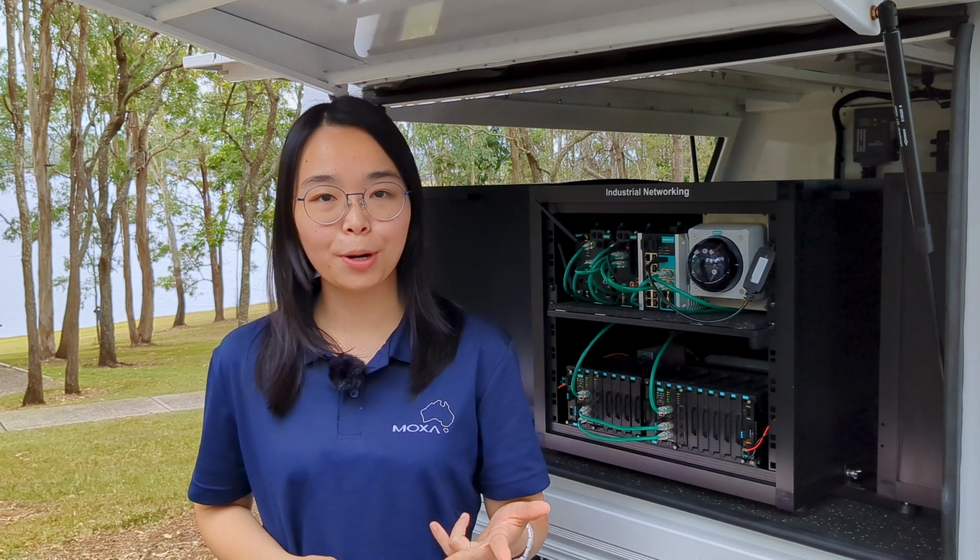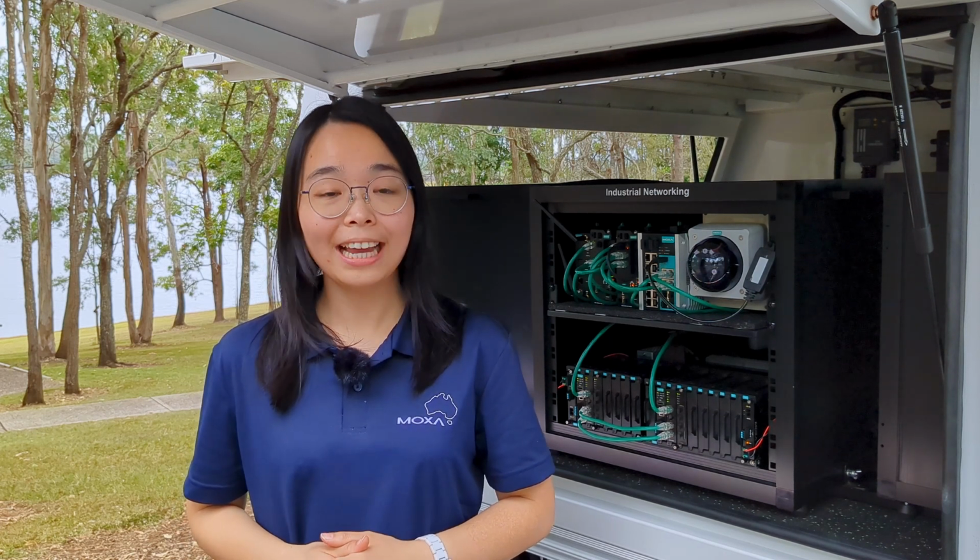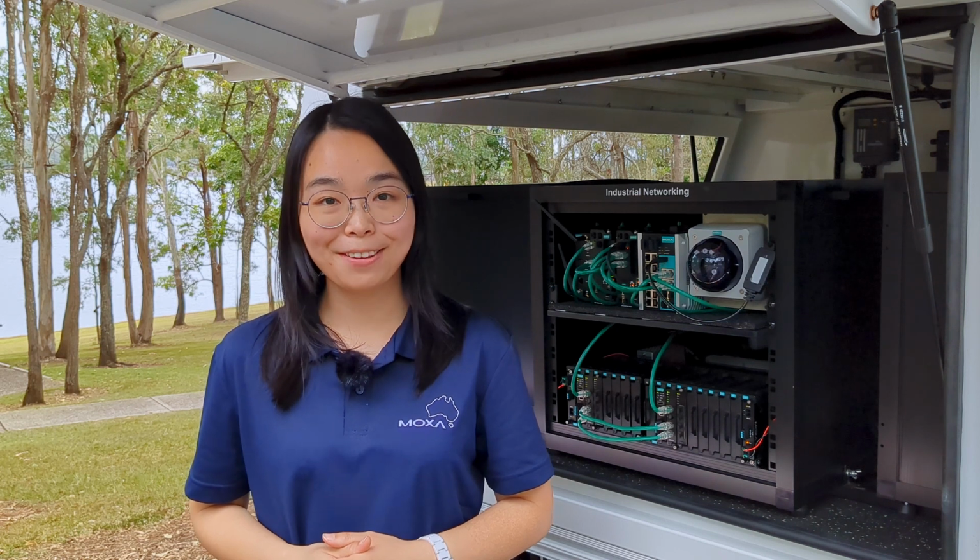In today's video, I covered 3 redundancy protocols: Turbo Ring, Turbo Chain, and MRP. All of them can be used to build station bus networks that comply with the IED to SCADA communication recovery time suggested by IEC 61850-5. Both Turbo Ring and MRP are based on ring topology and have similar operation principles. While Turbo Ring guarantees less than 50 millisecond recovery time, it can only be built using Moxa switches. If you need to mix different vendors' products in the same ring, MRP is a good option.